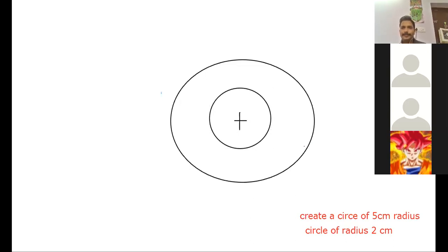Is it clear to all, right? Correct now, guys? So this is what I would do. Now where is the position of my follower? This is the line, and my follower is placed somewhere offset by 20 mm from here. So this is where the knife edge follower is placed. This distance from the center line of my cam is how much? 20 mm, because the radius of this circle is this much only. So it equals 20 mm. We are moving with the question and with the concept now.